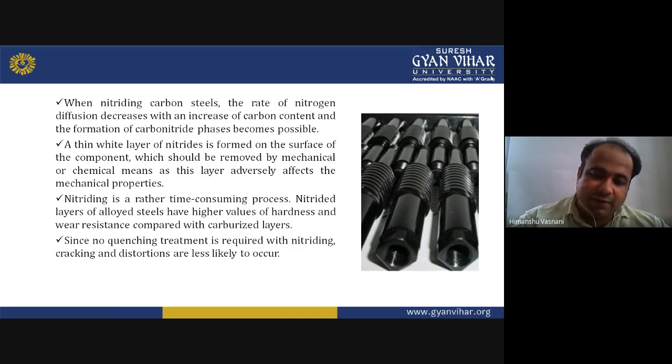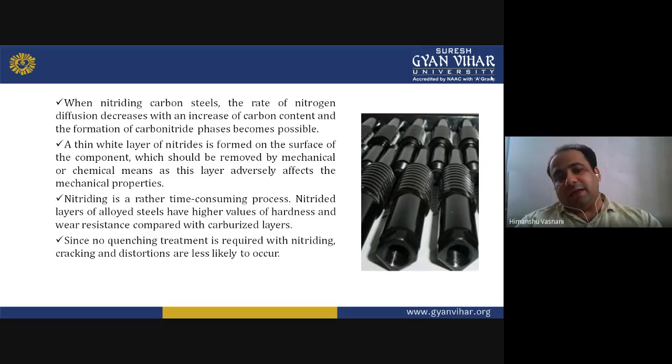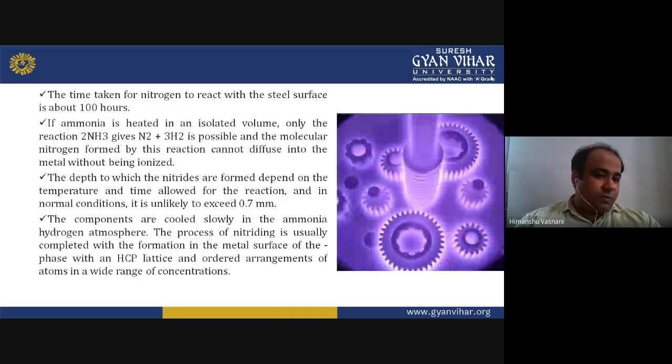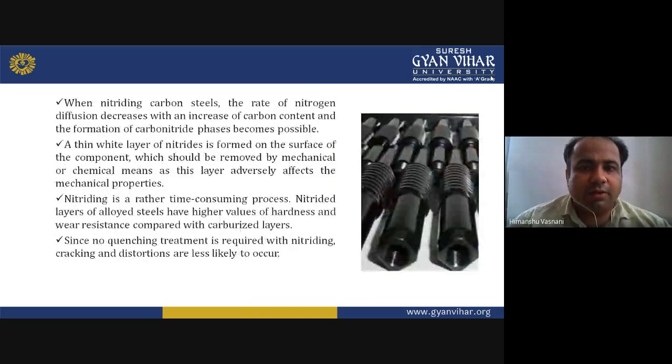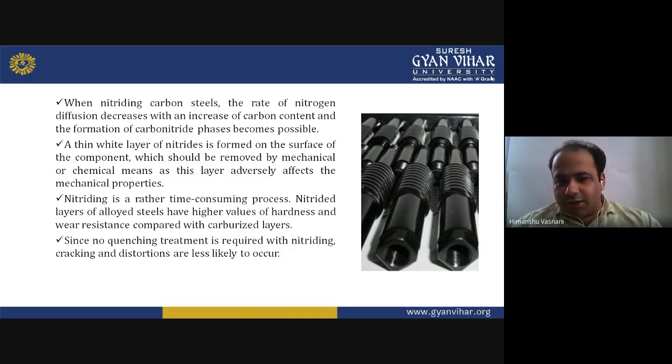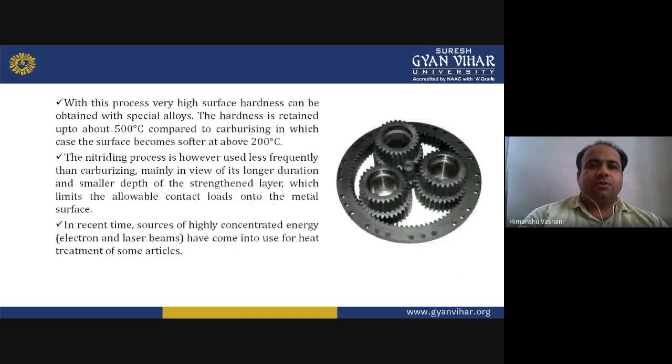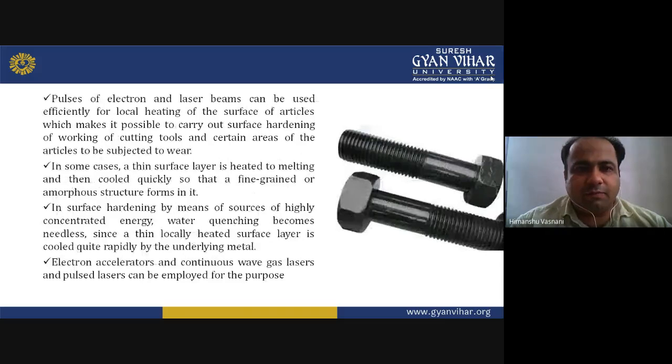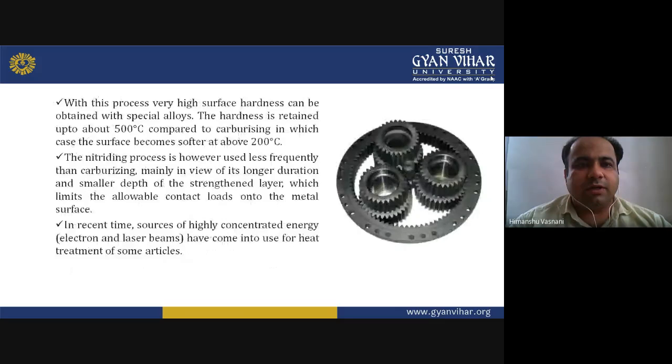So you can say that when this process takes about 100 hours, it is a time consuming process. Okay, so nitride layers of alloyed steels have higher values of hardness and wear resistance compared with carburized layers. So here no quenching is required with nitriding, so cracking and distortions are less likely to occur. So apart from this, let's start with our